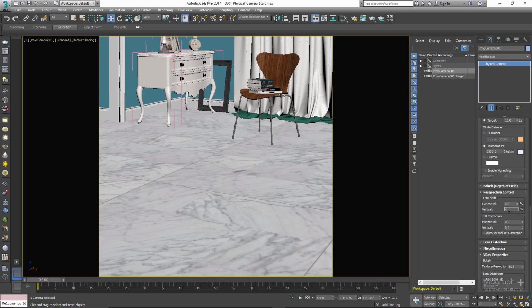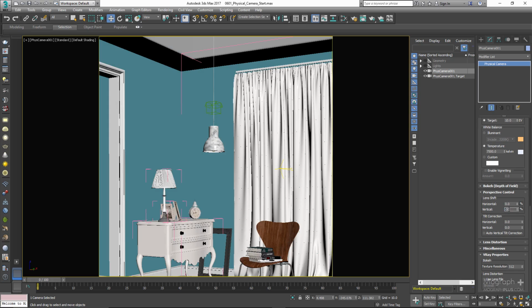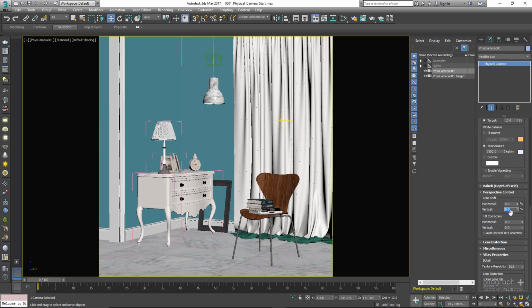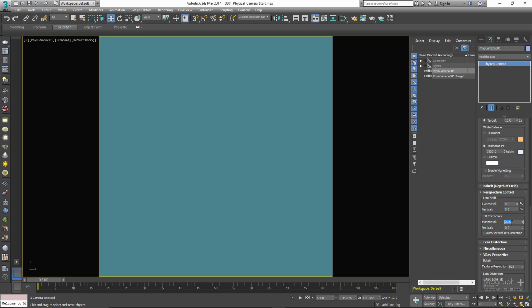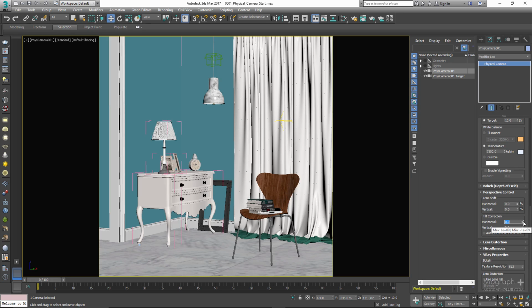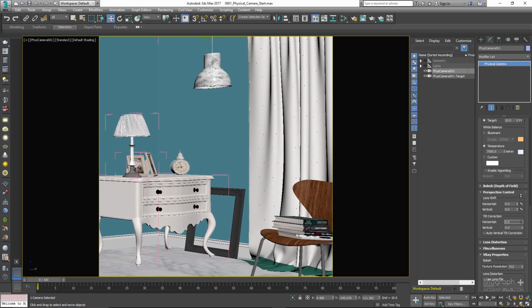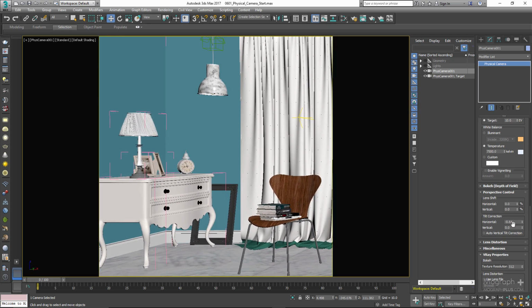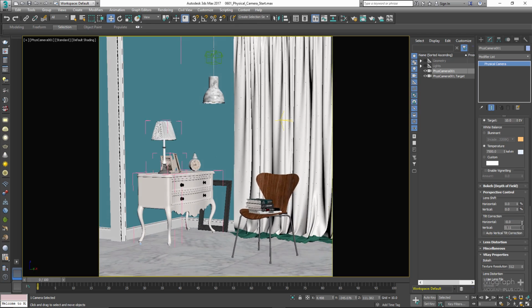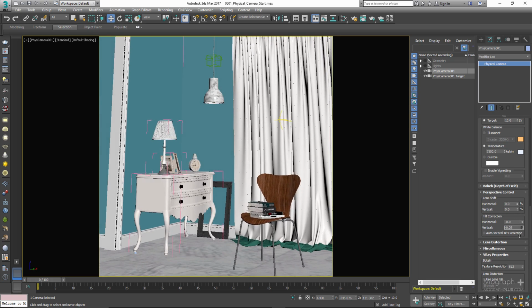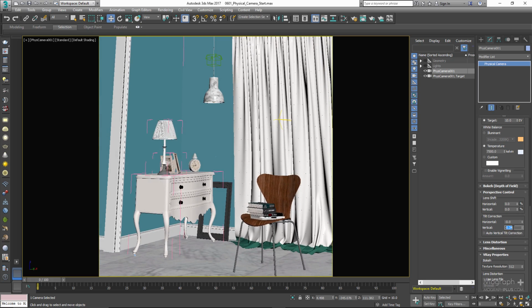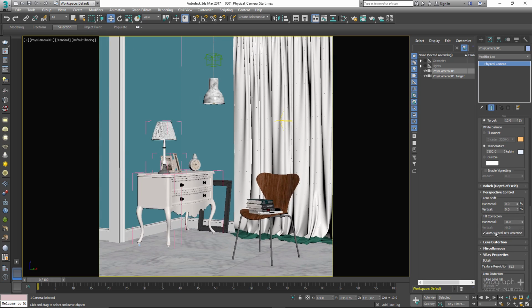In the tilt correction group, you can tilt the camera horizontally or vertically to correct the perspective, particularly in scenes where the camera is already tilting up or down, and to achieve the simulation of tilt lenses for 2-point perspectives. Also, auto vertical tilt correction. When this is enabled, vertical value will be set automatically to align perspective along the z-axis, and it is very useful in exterior architectural visualizations to correct the perspective.